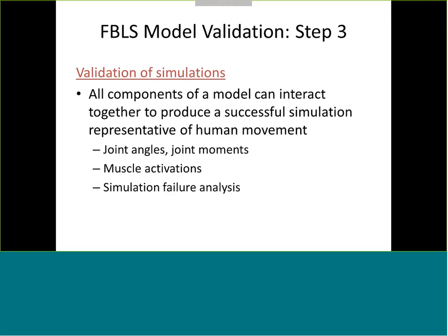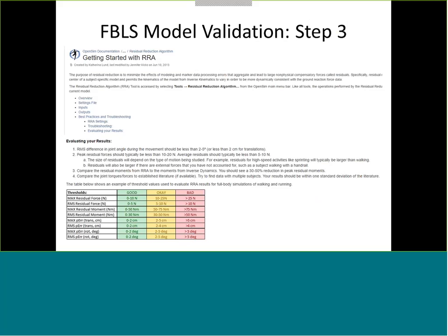Whenever you're creating a simulation, you also want to make sure to do a failure analysis to make sure that that simulation was successful and that the model output fell within the guidelines that the OpenSim team provides as a successful simulation. Depending which tool you're using in OpenSim, you can find in the documentation for that tool a number of different guidelines to evaluate your results, as well as thresholds for different model outputs that indicate whether that simulation was good, okay, or bad. And this is an extremely valuable tool to utilize whenever you're creating a simulation in order to evaluate your results and make sure that simulation was successful.